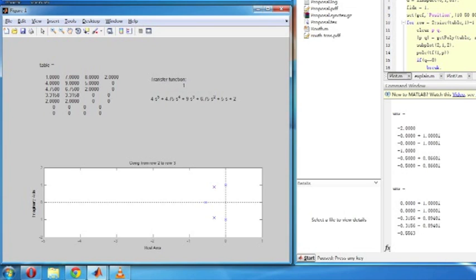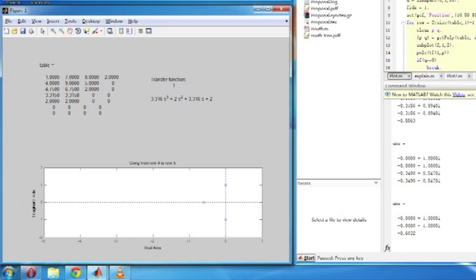We see that one of the roots moved off to -infinity and disappeared, as the polynomial finally dropped rank. In general, as we interpolate between the polynomials, represented by the rows, the roots on the j omega axis never move, and the roots never cross the j omega axis. Thus, the stability of the reduced polynomial translates to the stability of the original polynomial if all the roots that went off to infinity indeed went to -infinity instead of plus infinity.